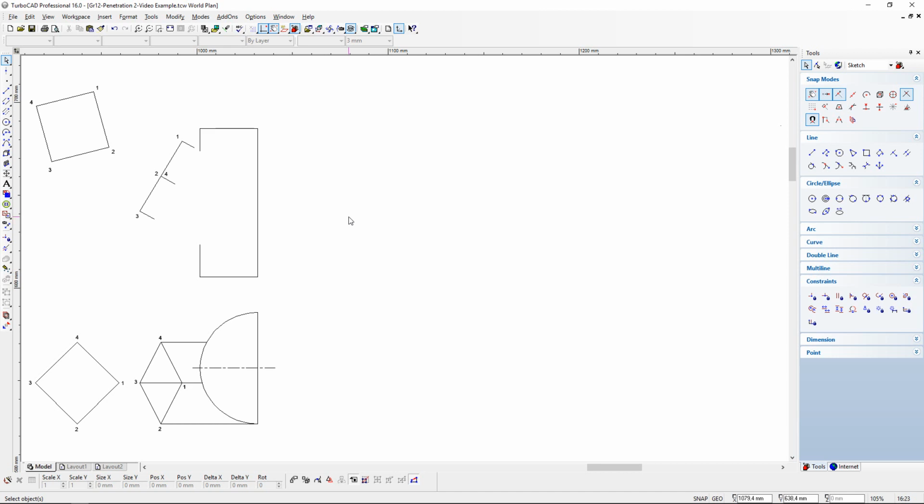In front of us, we have an interpenetration where we have a square prism penetrating a half cylinder. We have our front view here at the top and the top view at the bottom. Therefore, this drawing has been provided to us in first angle. So what we need to do is make use of our top view to determine the depth of the penetration